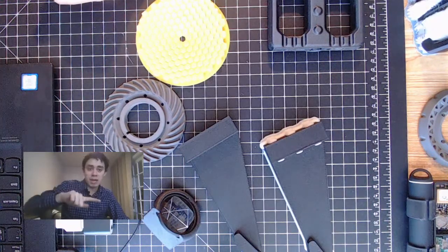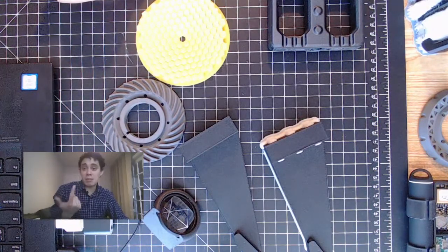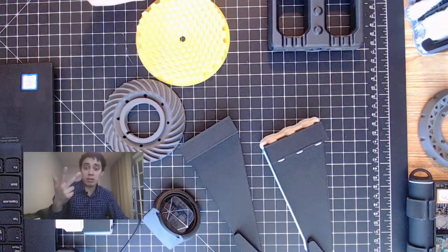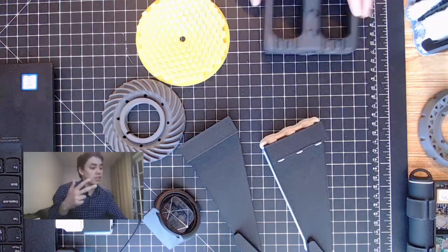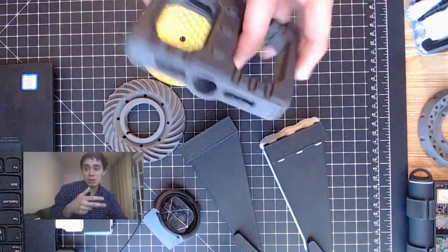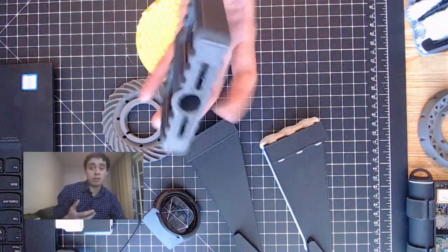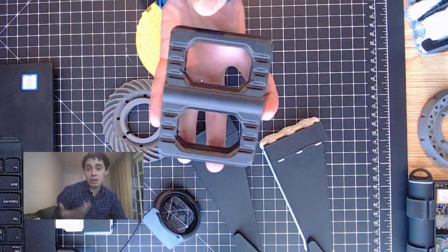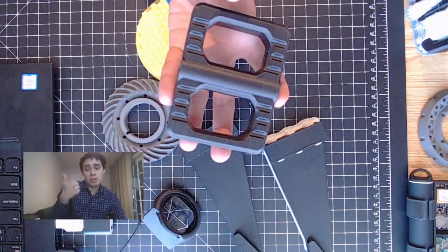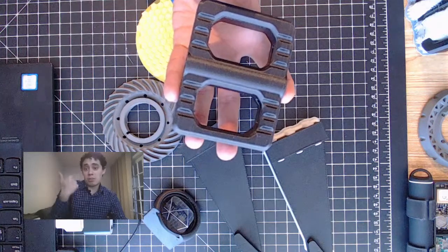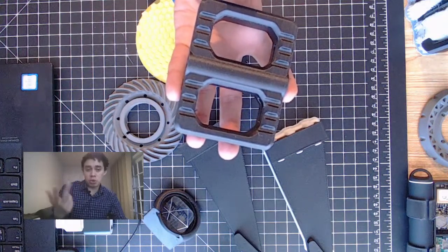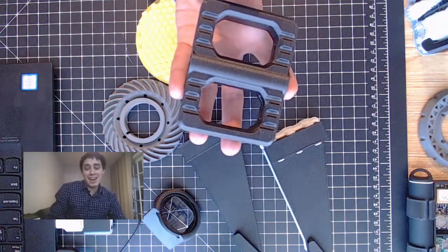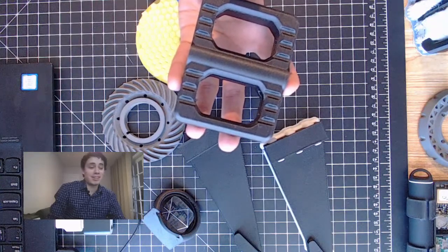Will changing my part orientation affect the amount of supports that are required for this part? And third consideration, appearance. Will changing my part around change the way that I'm able to describe a particular shape and the finish of my part? So strength, material, and aesthetics. Those would be the quick TLDR of today's conversation.